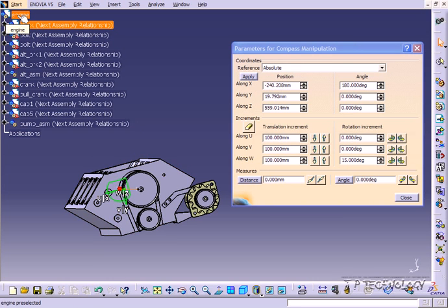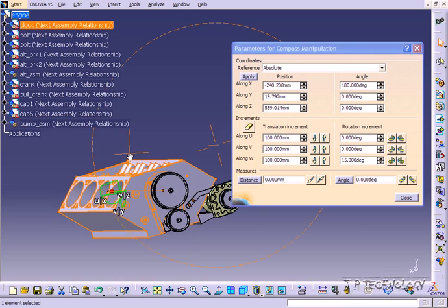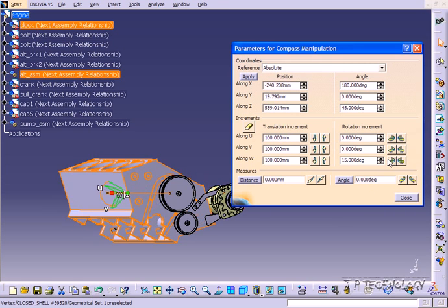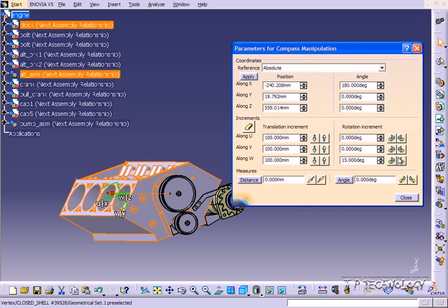So to start off, let's move just the engine block. Let's double click engine, just highlight the engine block, and we have it rotating around the W axis at 15 degrees. So let's just try it out, see? And you can see how the whole block is rotating 15 degrees every time we click. And again, you can do the same thing if you click on the plane and you can rotate about it too. Now let's do the entire assembly.